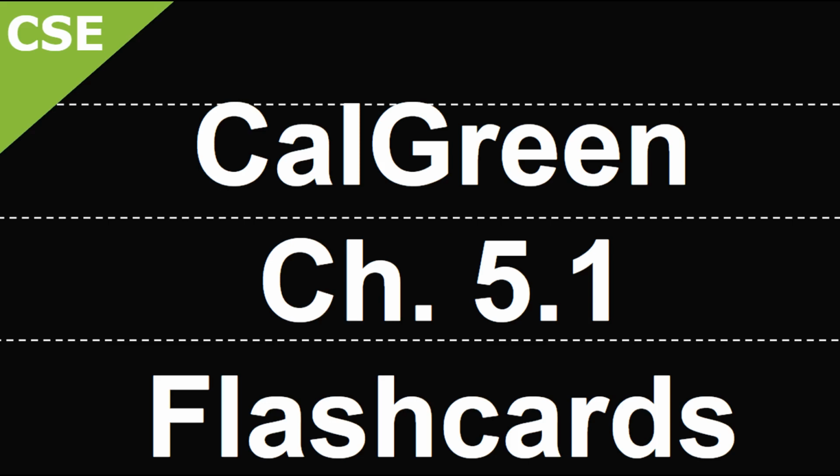So the final count of 55 total actual parking spaces means we need to provide 3 electric vehicle charging stations, 2 DCFC EVSEs, and 1 level 2 EVSE. Again, there are many ways to solve this problem. This is just one way to solve this problem.